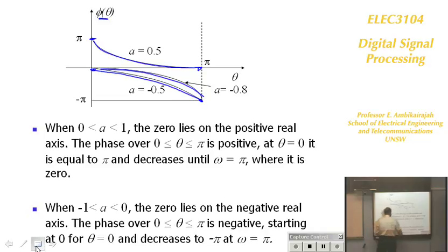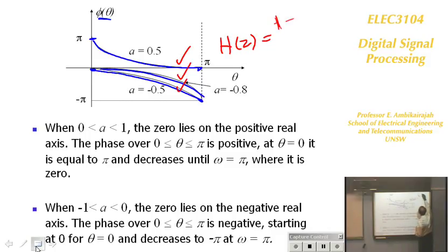You can see the magnitude remains the same, but the phase is different because your transfer function h dash is z minus 1 over A. So the other way around is 1 minus 1 over A z to the minus 1 divided by 1 minus A z to the minus 1. That's your transfer function. This is your pole. This is reflected, so that's your zero.